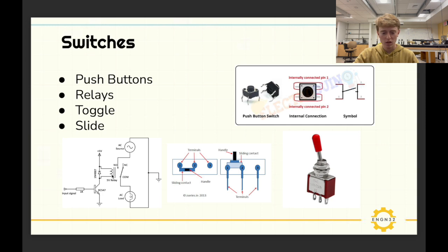Right here you can see this little coil symbol that I'm circling on the screen, which is basically an electromagnet. When I turn that electromagnet on, in a normally closed system, it pulls the contact to the other contact because it is magnetic, and that completes the circuit.